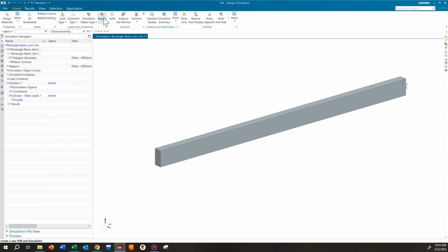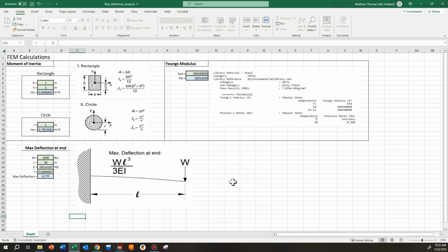And we're just going to go through this. Again, this is a simple one. So let's think about what we've done so far as the calculations go. We have weight, length, Young's modulus, and then the moment of inertia. Moment of inertia is, again, the shape of our beam. We have already done that because we created a beam with these specifications, the base of 1 inch and a height of 2 inches. We have done the length because when we created the beam, we made it 36 inches. So we've got 36 inches here, and because of the way that we created our shape, we have that moment of inertia here.